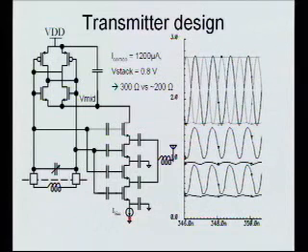The problem with the transmission line is that we're at about 900 megahertz, so the wavelength is like that, and your chip's like that. So getting a transmission line on chip is still not real practical. Typically, transmission lines start getting used at about 5 gigahertz and up. Yeah, that's where it even begins to be practical. And most of them are more at the 10 plus gigahertz range, at least on chip.